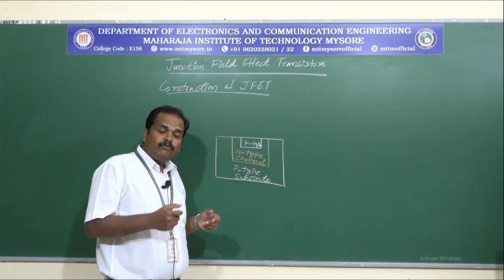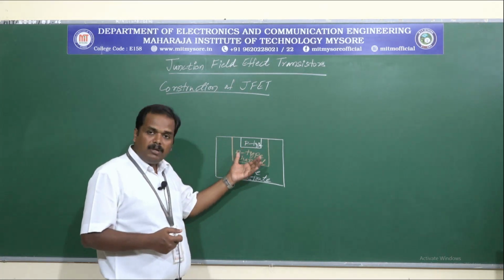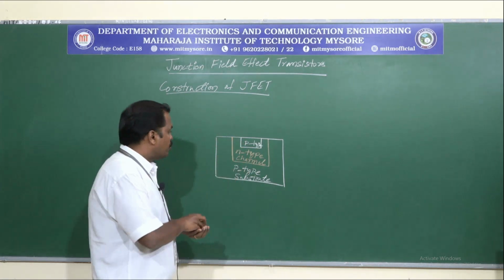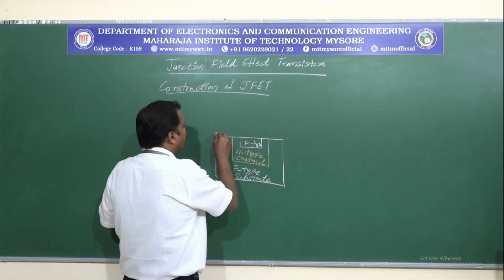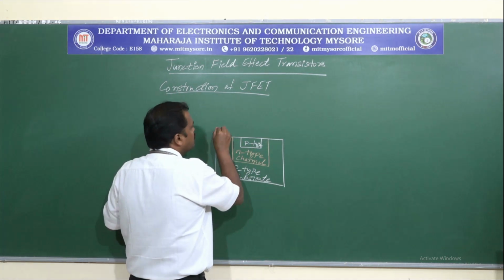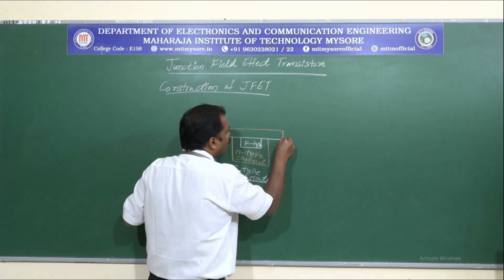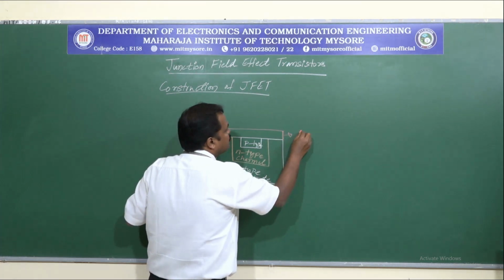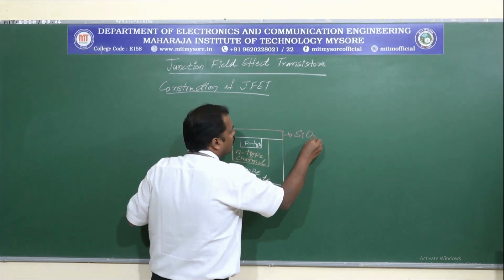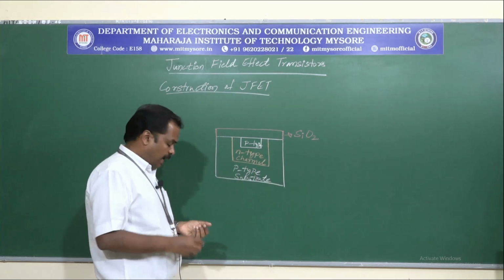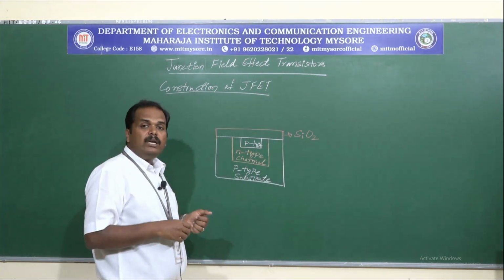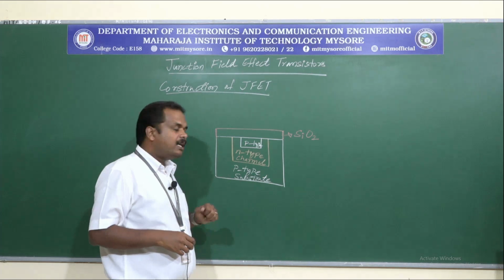Now to facilitate the terminals, upon the surface of this we'll deposit a layer of silicon dioxide. So this is made up of SiO2, and now finally we'll deposit the metal layers.